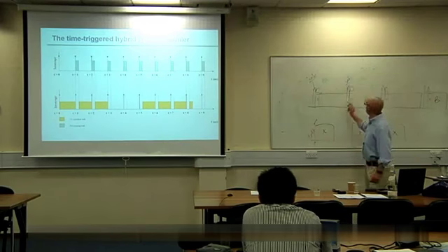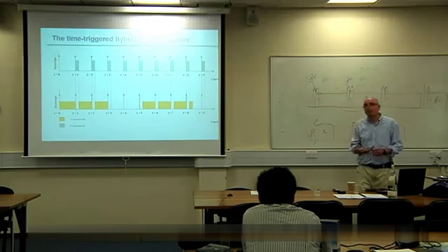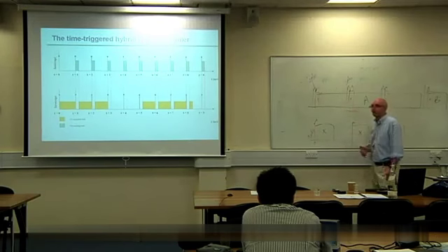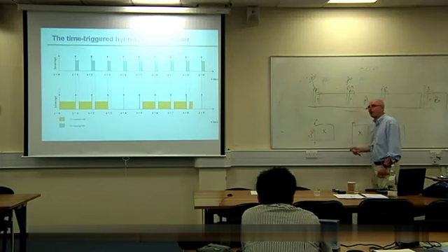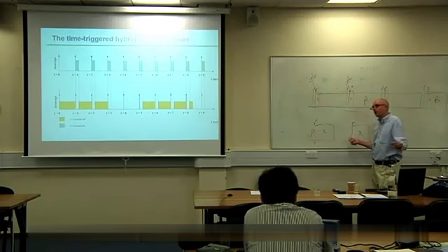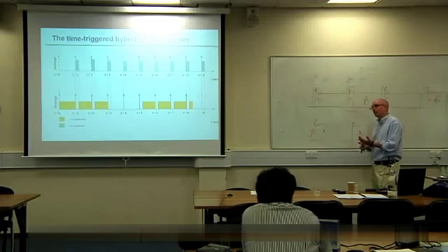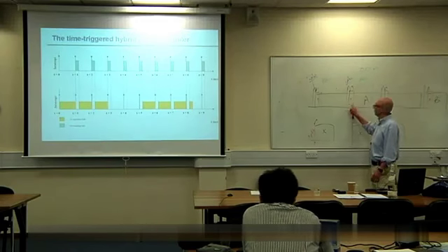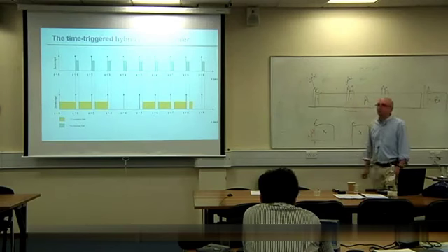And the time here, we probably have to work out from the data sheet, or usually, because they don't usually give you enough data, you have to work it out practically, how long it takes the thing to get into idle mode. And you have to experiment a little bit, because it's going to essentially have to finish the current instruction, whatever that is, go into idle mode. Then the jitter in this will be the same as the jitter here.